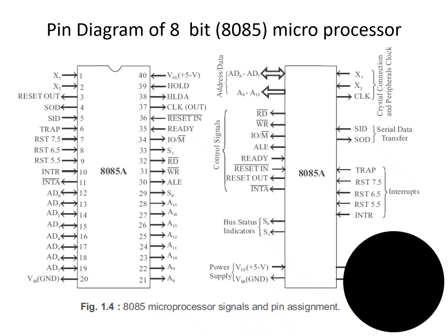There are several control signals exhibited by the 8085, and a 16-bit address bus, A0 to A15, and the data bus is AD0 to AD7. With all this, the pin diagram of the 8-bit microprocessor is built.